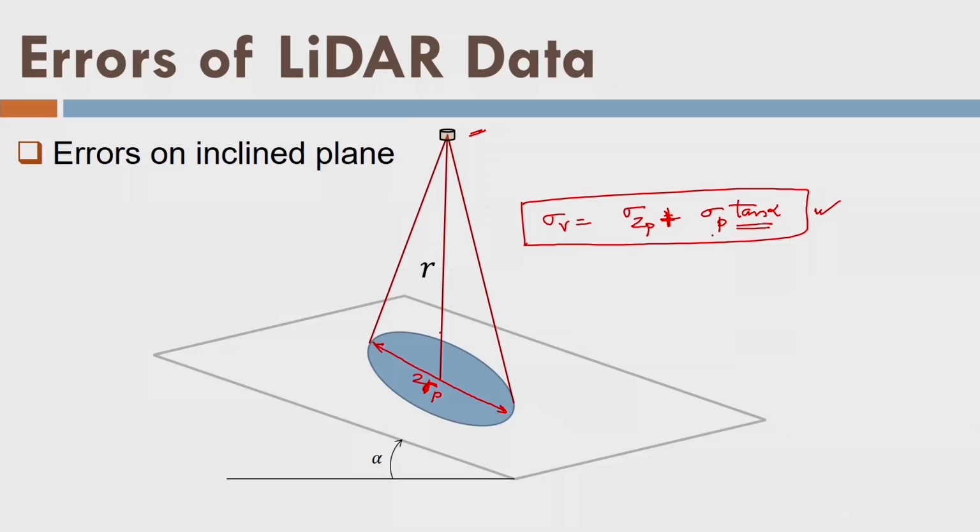The first is relative error. In case of relative error of one swath, we try to fit a plane to the particular swath data. For the given data, which is like this, few of the data points may be in the plane, few may be lower than the plane, few may be above the plane. So, I have fitted a plane.